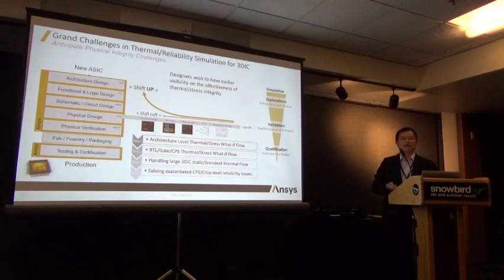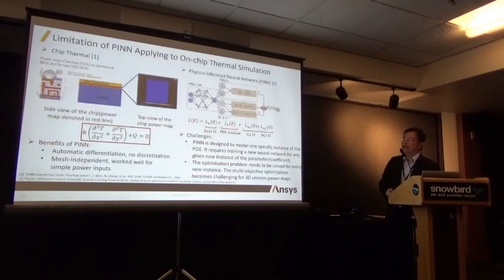Secondly, when you have a detailed placement and routing, they also want very fast simulations in terms of thermal and transient thermal simulation, and also, of course, dynamic voltage drop simulation. And then reliability will come into the picture as well, because it's all thermal related.